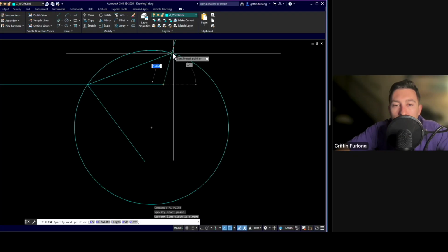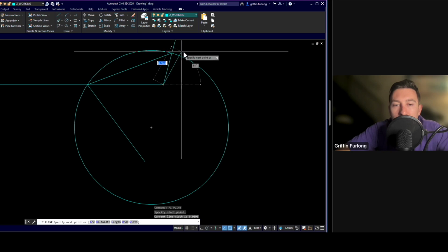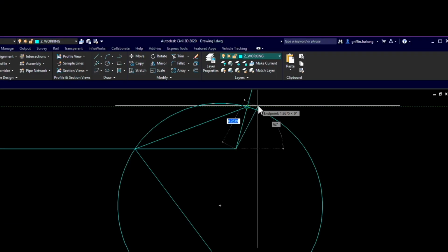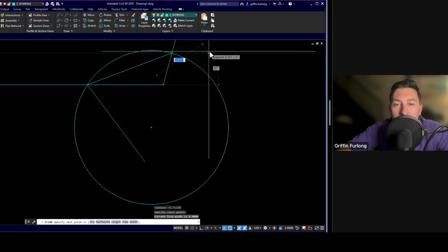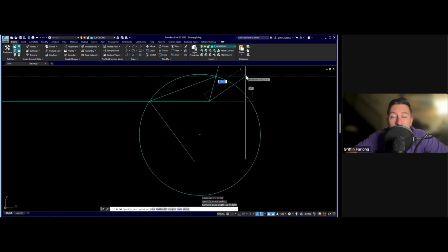I'm going to hover over this point, and let me kind of start moving my cursor a little bit. Notice how there's that dashed green line up top. Again, that's because my snapped reference line is on. So really all that helps do is kind of locate a point that might be perpendicular to a line, or a continuous construction line of that point. But I don't really use that one that much.